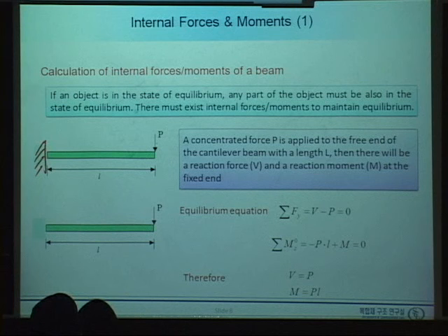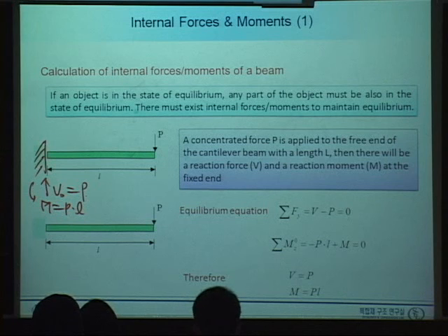Of course, we can calculate the reaction force V0, which should be simply P, and the moment should be P times L. And this again is calculated from those two force equilibrium equations, both the y-directional and the moment equilibrium.